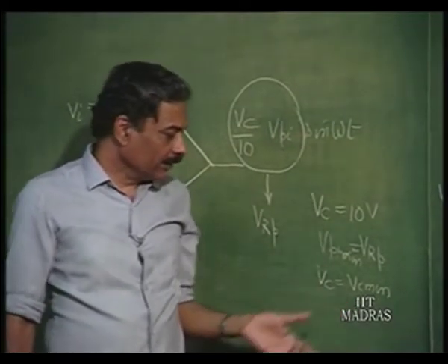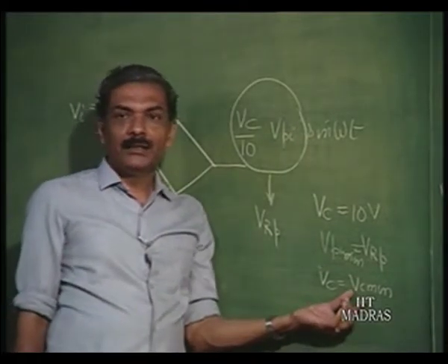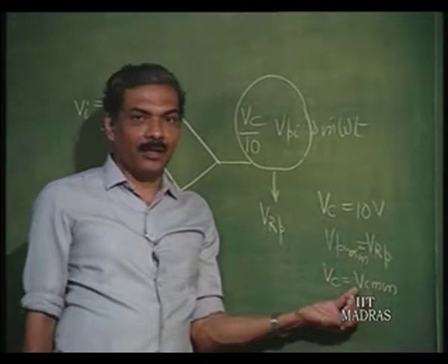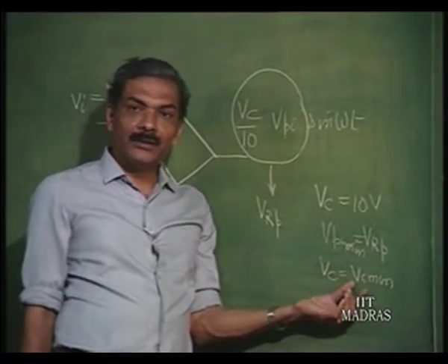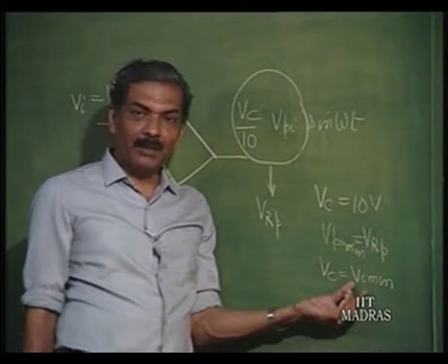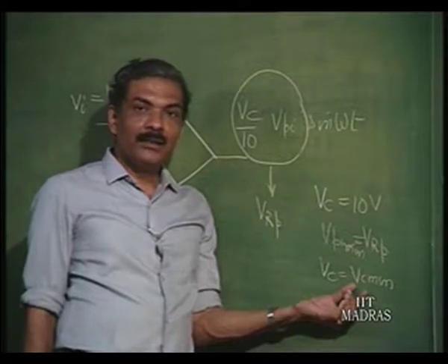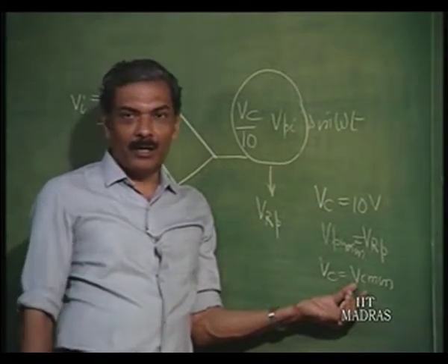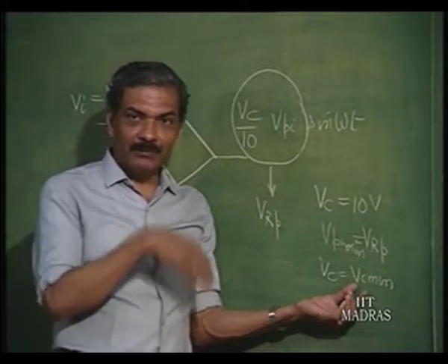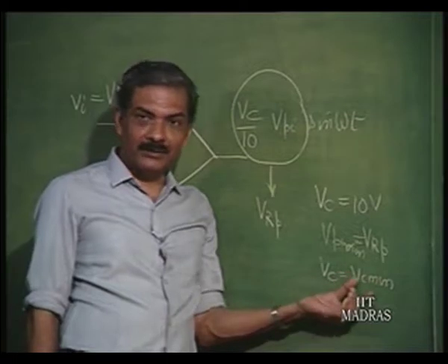So, this particular thing, this Vc minimum, is going to be fixed by what will be the order of minimum voltage that is necessary for the multiplier, at which the multiplier will satisfactorily multiply and act. This is normally about 10 times the offset voltage of any of the op amps and things like that, that are used in the multiplier. Okay. So, that there is certainty about the value that you are considering here.